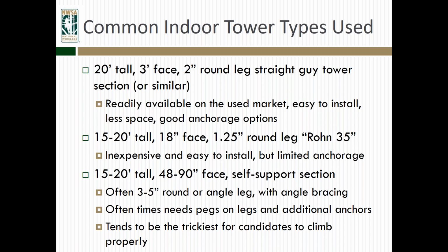Occasionally, if the leg is too big for their anchors, for their Y lanyards, you need to install some straps that are accordingly placed so that they have ways to properly climb the tower, not out-climbing the lanyards, things like that. So think about where your anchorage points are.